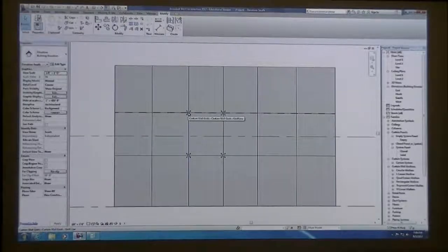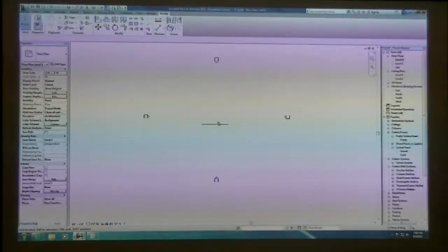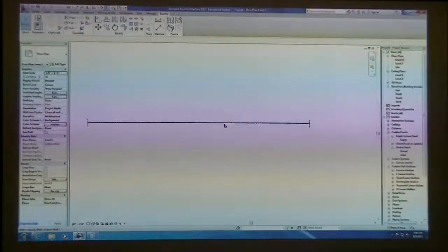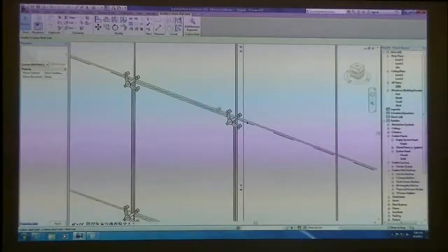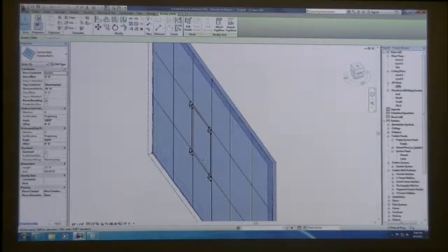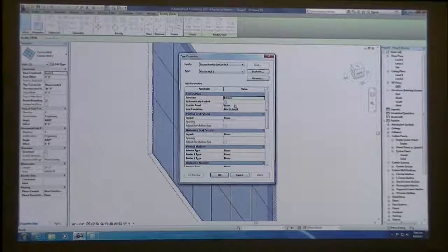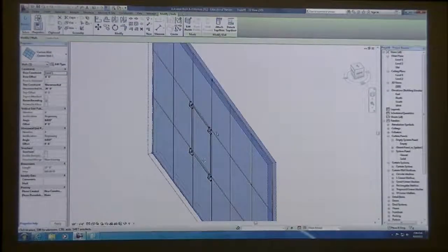Jeremy, I think the offset that we did moved the glass panel back. Because if I look at mine in 3D and Ryan has the same thing, it looks like it's off the wall. Yeah, that's because if we actually click on the overall curtain wall system, and look at the edit type for that wall and scroll down, that's because the other glass panels that are associated with it have some offset, probably at 1.5 inches that were already inherent with it. So as we change all of our glass panels, they'll move back into place. Okay. So yeah, it will be offset at the current moment.